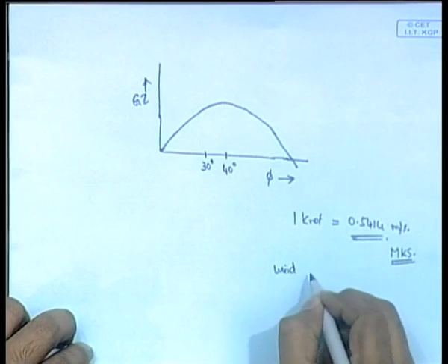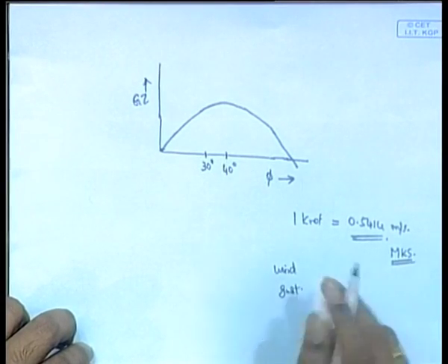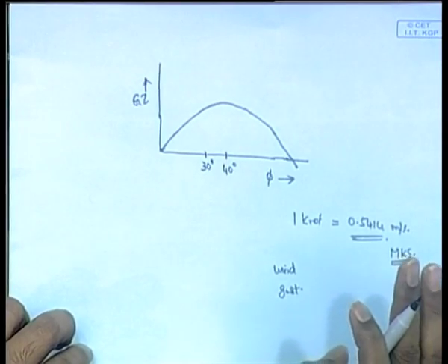Wind, we call it as wind and as a gust, two slightly separate meanings. It's like the difference between a steady force, a constant force acting for a long time on a ship, and a sudden impulse. You must be familiar with the difference between the two. By a sudden impulse, we mean a very strong force acting for a very short time. So, it produces a very strong impulse on the ship or any body. That we call a gust. That means a very strong wind is acting for a very short time.